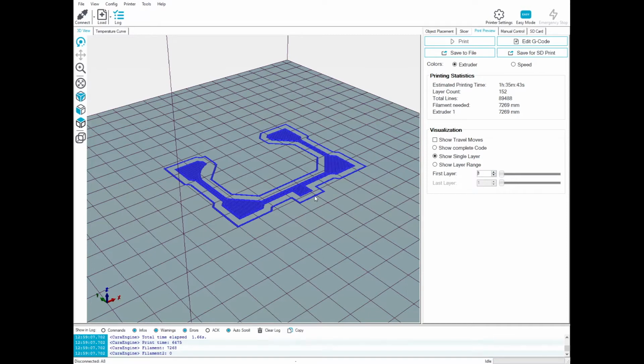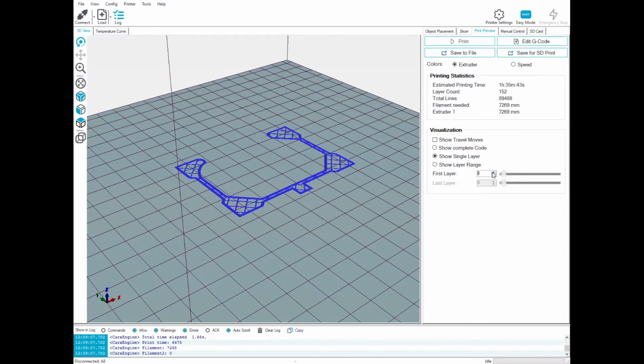That also shows you this is where the part's going to be printed. And if those outline beads of plastic don't stick properly to the print bed, then your first layer probably also is going to have some adhesion issues. It's a very quick gut check to figure out if your bed is properly leveled. So okay, first layer, second layer, third. This is really just a convenience thing. You don't have to check this every time.